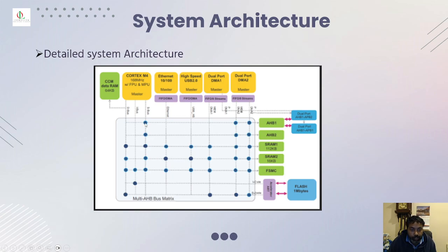The blue dot represents that there is a connection, an access from master to slave. If you don't have the blue dots, then that means the master via that line can't communicate with the slave. For example, we are learning Cortex M4 architecture. So if you take the D bus, the data bus, that's the first one. If you want to access any data from SRAM or SRAM2 or external memory, you can use the D bus, and you can connect and fetch data from these three.